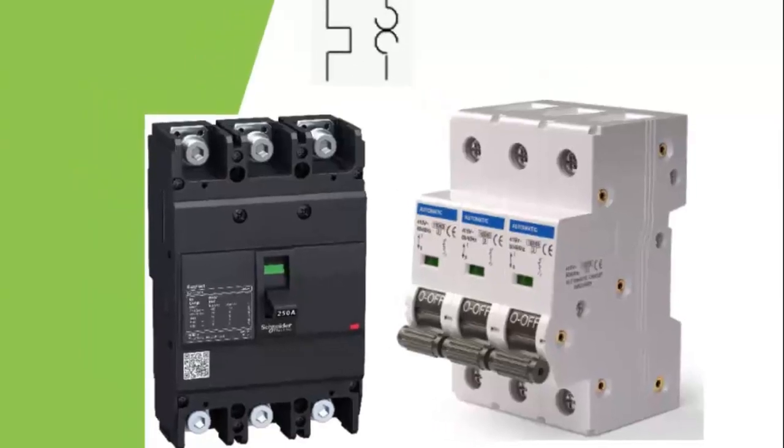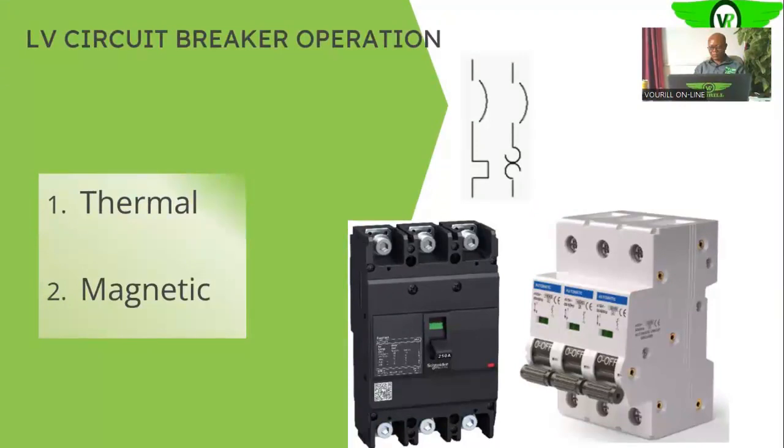Then the other category of the low voltage circuit breakers that we will be looking at are those that are controlled magnetically. On the thermal element, there must be some time delay for the heating element to get heated up to the extent that it causes the bimetallic strip to bend. In that amount of time, a lot of things can happen, especially when we have intense fault currents like short circuit currents that are more than 10 times the rated current that is supposed to flow through the circuitry.